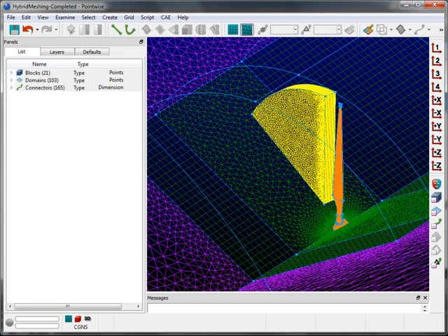So how do you go about creating a mesh that achieves this using either structured or unstructured meshing strategies? Well, using a structured meshing strategy would tend to give you a higher accuracy solution. However, creating a structured topology for a complex geometry such as this is very time intensive, whereas creating an unstructured topology for a geometry like this takes very little time, and unstructured meshing tends to provide a little bit more flexibility in terms of resolution control, like localized clustering. So actually being able to combine structured and unstructured meshing strategies into a hybrid meshing approach is really a good compromise between meshing effort and accuracy.